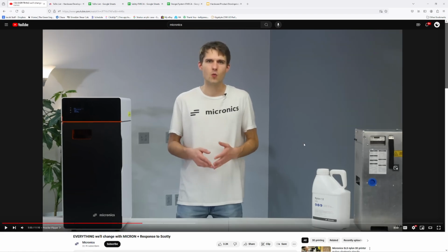Also, was tolerance stack up done here? When that thing heats up, is it clamping down on that flipper? Did you give enough space? Did you set it up such that, hey, this thing is going to operate when it's heated? Okay, now it's going to shrink into the tolerance that I need, right? Is the stack up done for that?